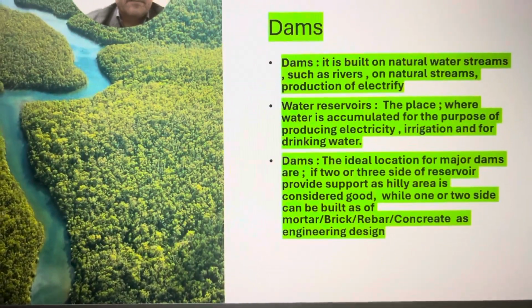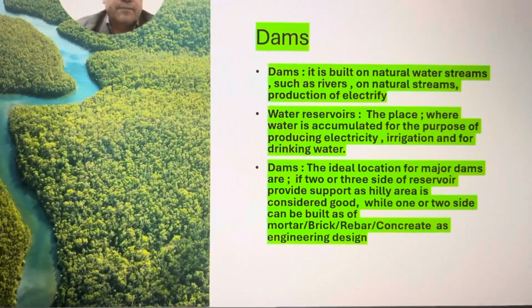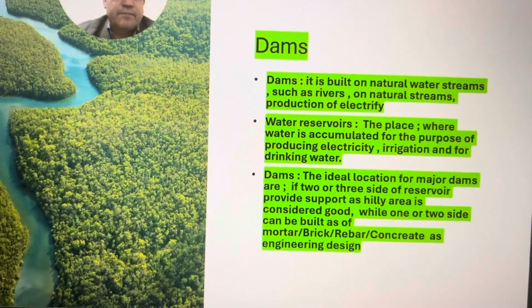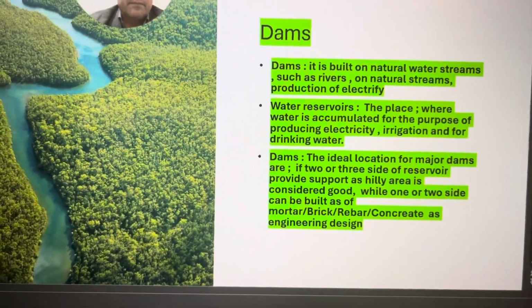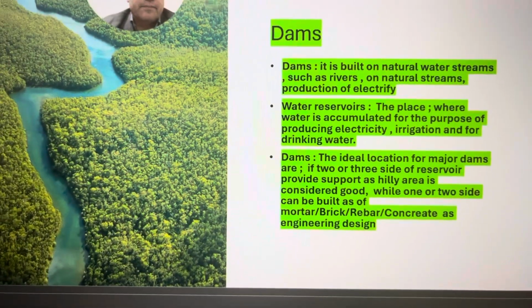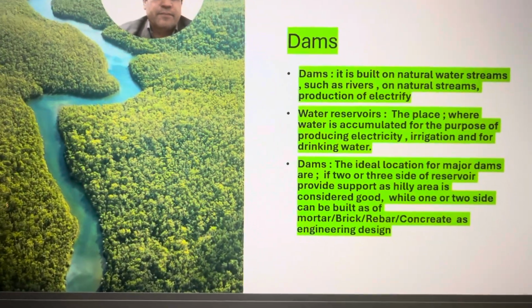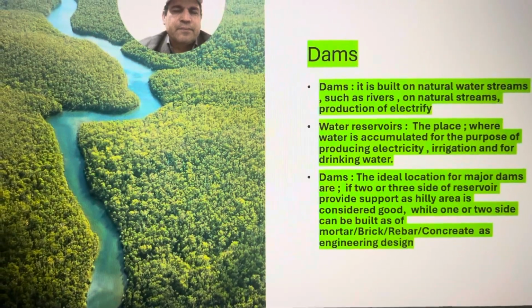The ideal location for a dam, as I think as an engineer, is where the reservoir has a hilly area on two or three sides, and there is no fault or fold in that area.